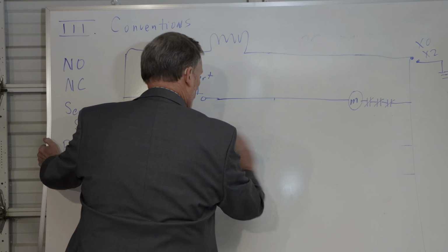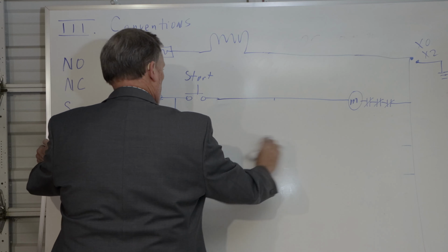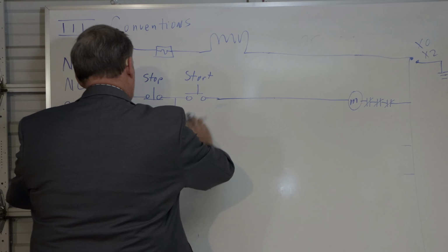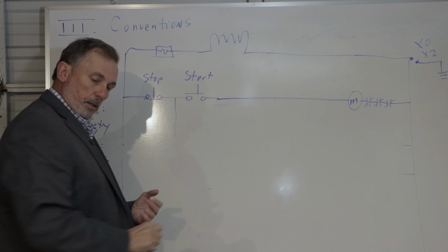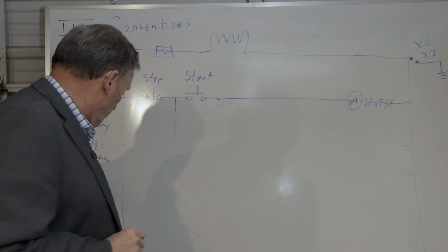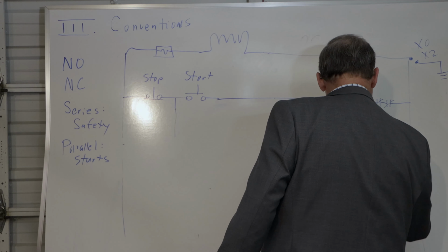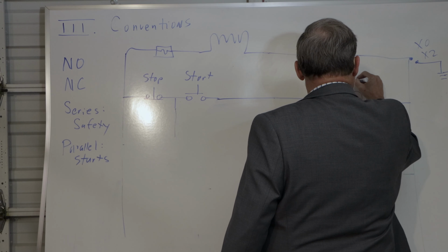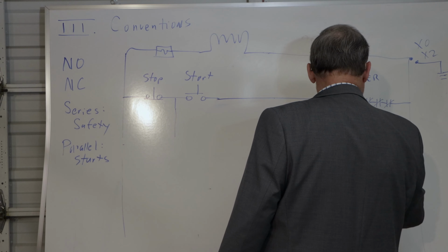In other words, it needs an oil bath to operate, like maybe a drilling machine or a heavy piece of equipment. So when I start the equipment, I don't necessarily start my big motor. Let's say M2, which might be the lathe. M1 is an oiler. M2 could be a milling machine, let's say.